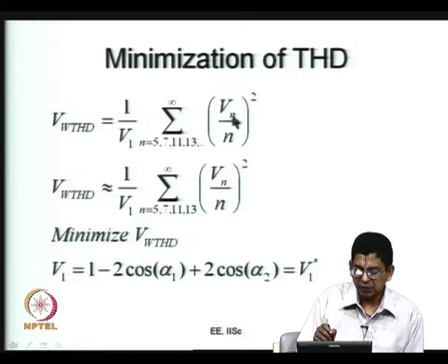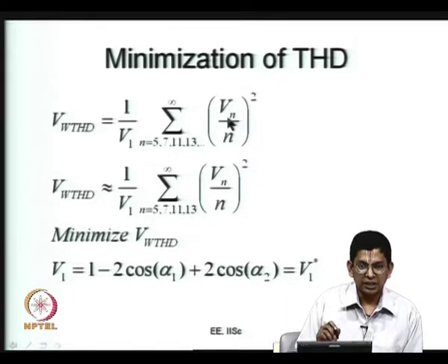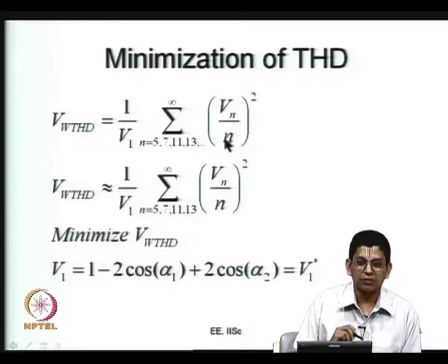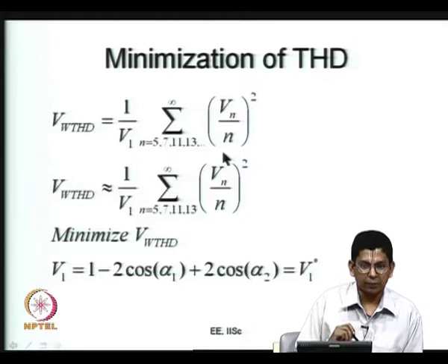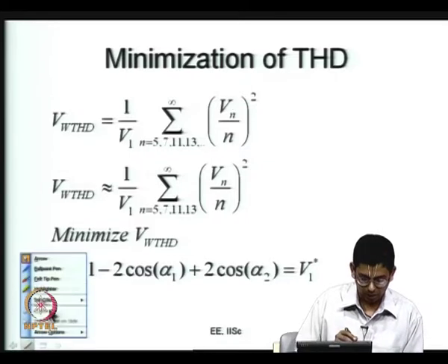Now, you see that there is a factor Vn. What is this Vn? Vn is the nth harmonic voltage. The nth harmonic voltage sees a harmonic reactance which is n times that seen by the fundamental voltage. So you have a Vn by n factor here, and that is whole squared. I have missed out a square root on this, I am sorry.